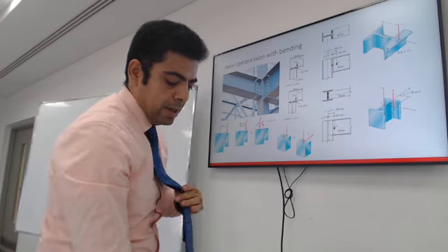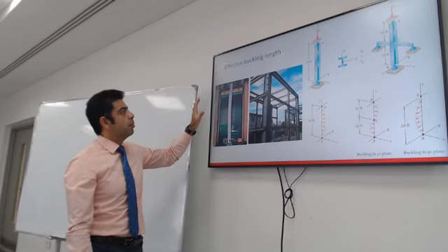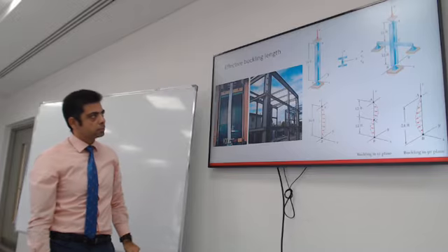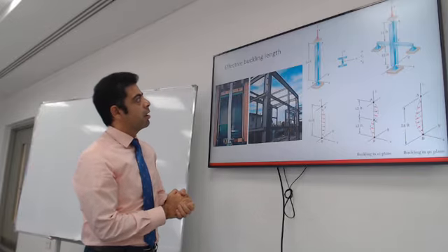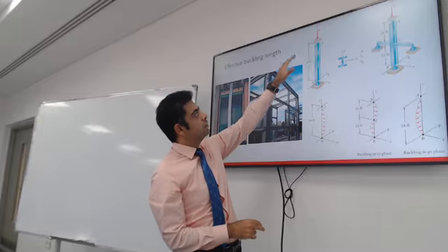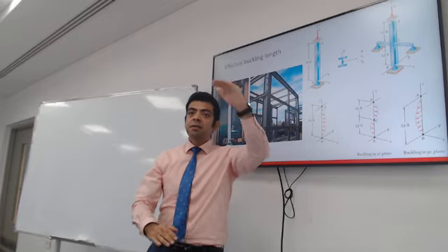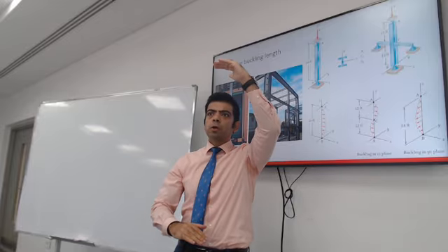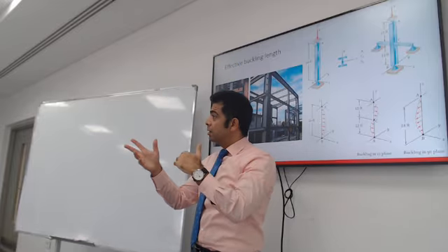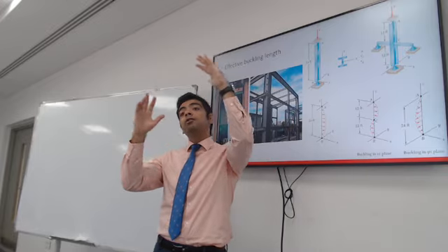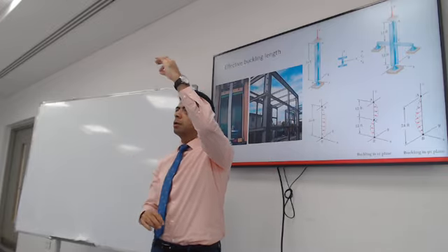All right. The next thing we talked about was the effective buckling length. So let's say that we have a column that is spanning a double height, like 7 meters or something like that. 7 meters is like 2 floors. What's kind of the average height of a floor? 3 meters, 3.5 if you're creating a bigger space. So 7 meters, this is a pretty tall column.